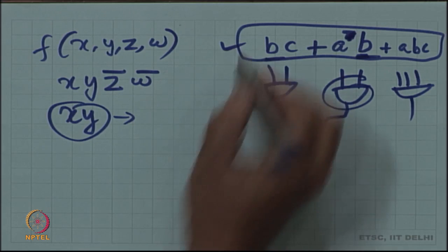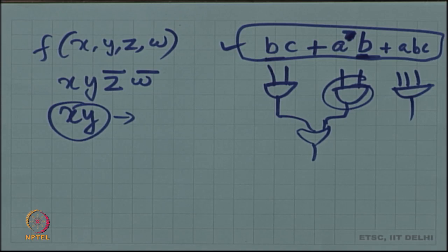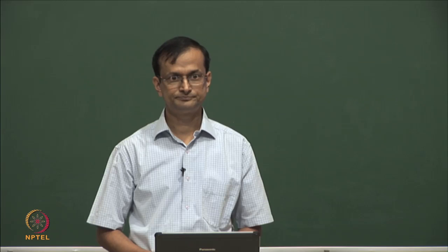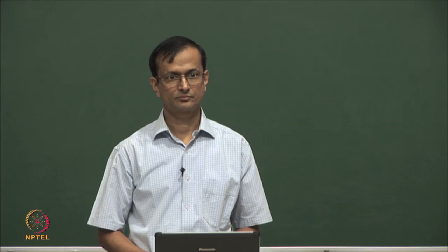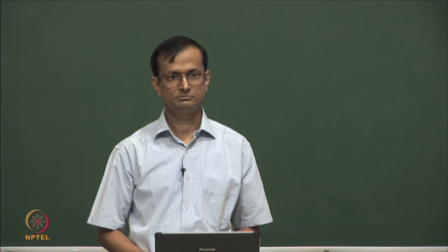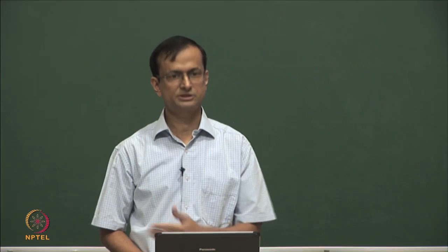So, somehow this is the last stage of all the optimizations, and we want to evaluate how good it is without generating a circuit out of it. So can we put it this way? For example, if I take a 2 input NAND, then for each literal in that expression, I will be consuming one stack of P and N in a complementary MOS implementation. That is what this translates to.